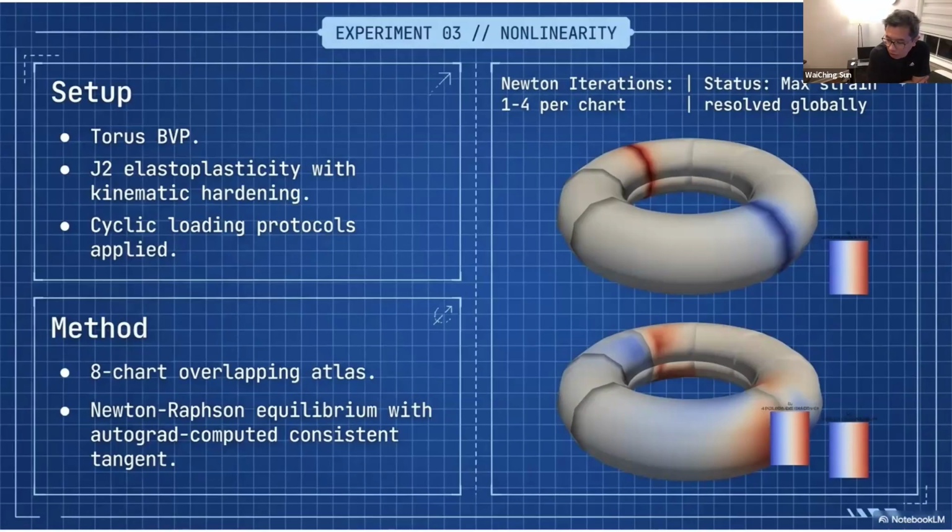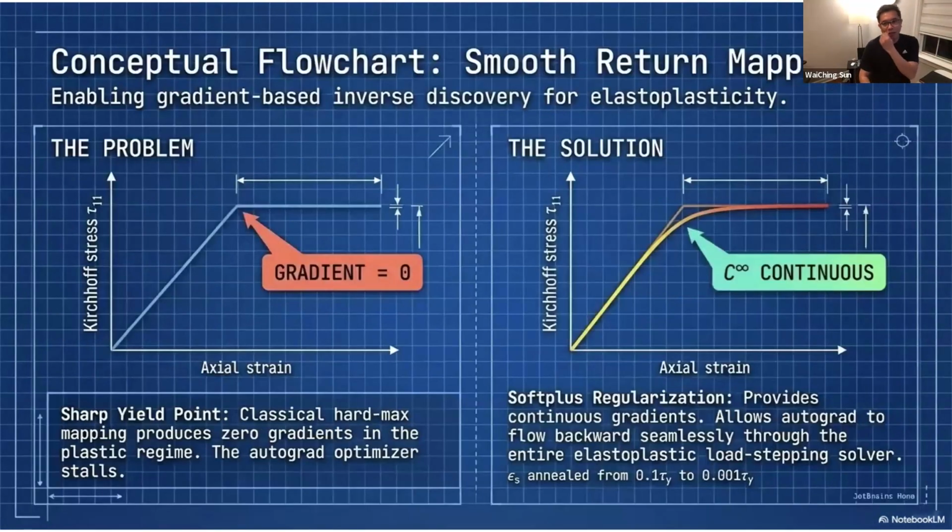We want to know whether we can use this technique to recover the back stress, and from the back stress, back-calculate the kinematic hardening coefficient and the initial yield surface. There's some difficulty there, and my student found that in the inverse problem, if we're solving the elastoplasticity problem, the gradient vector has a jump, and that makes the inverse problem really hard.